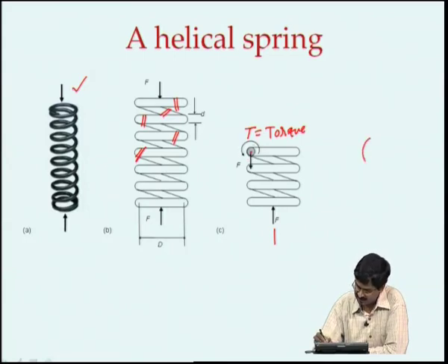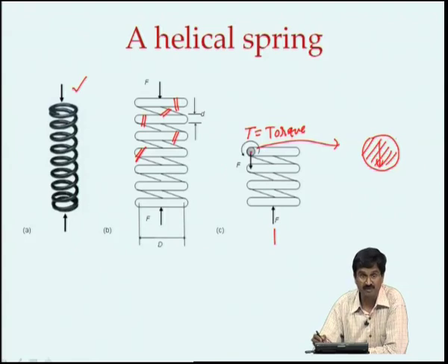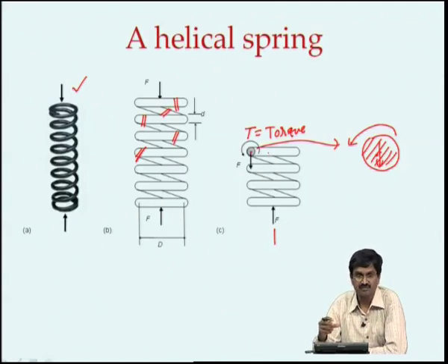So, if I were to take this rectangle cross section and blow it up, okay, there is one force that is acting over here, that is parallel. So, that is called the shear, and also there is a torque about an axis perpendicular to the cross section area, that also causes shear. So, this is a case of a structure that is deforming where there is shear due to this vertical shear force, a concept we had discussed in the context of bending of the beams, and also we have the torque now which also causes shear, and that shear effect is what we need to take in order to analyze this.